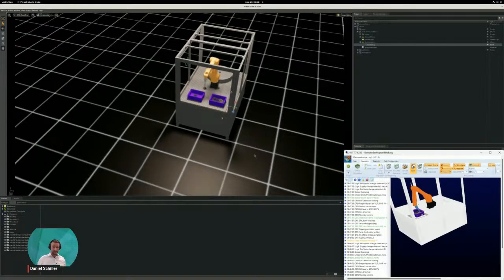As you see here, additionally, we are using a new simulation environment compared to the slides you saw previously. We are using currently the NVIDIA simulation environments, Isaac Sim and Isaac Lab, focusing on Isaac Lab because it has a GPU accelerated physics calculation, not only a GPU accelerated ray tracing, but also rigid body GPU accelerated calculations. So it's way faster than usual running other systems.